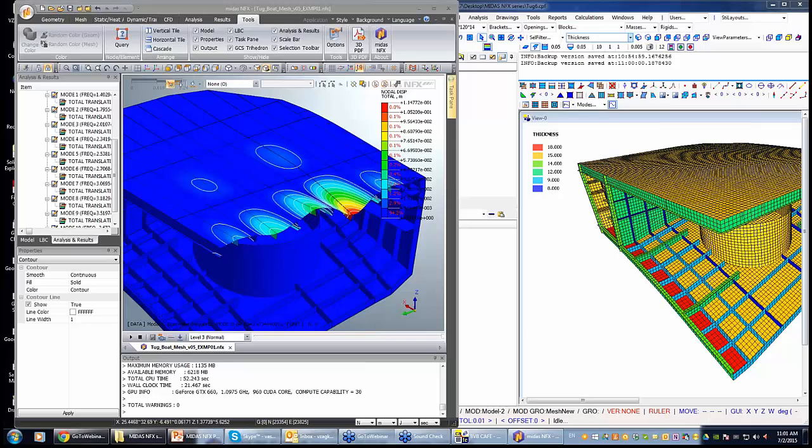Can CAFE support modeling of combined stiffeners, plate and bar? Yes, that's a very basic function of that. And also the second question, what type of analysis does CAFE support itself? So basically CAFE is a ship structural modeler and preprocessor. It's not a solver on its own, so this is why we are also integrating the two platforms.